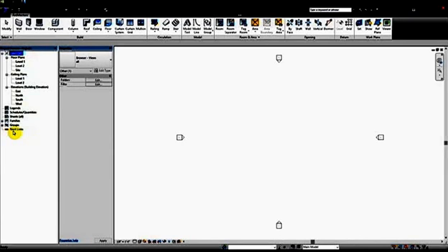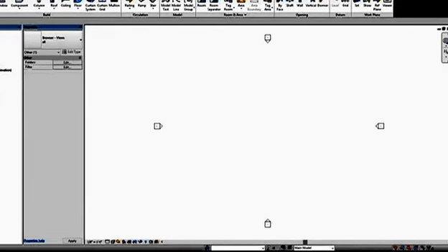any groups you create in the project will be listed under groups. Revit links is when you link a Revit model into your model. They'll show up underneath the Revit links. This is most commonly used, like at work, where I use it for linking consultant models, structural and MEP models, into our Revit model.